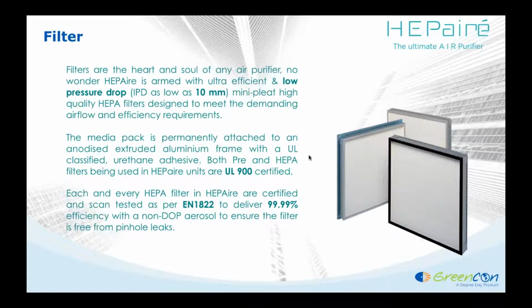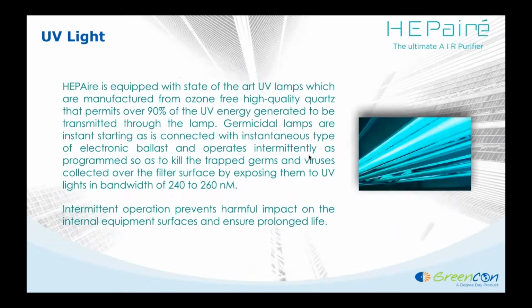So if you're using a right-size HEPA, it can last really long. The important fact is that they should be properly tested. It should not be a generic HEPA or a true HEPA or a semi HEPA or whatever we may name it. It should come with its own test certificate as per EN 1822 to deliver whatever it is claiming. It could claim less or more.